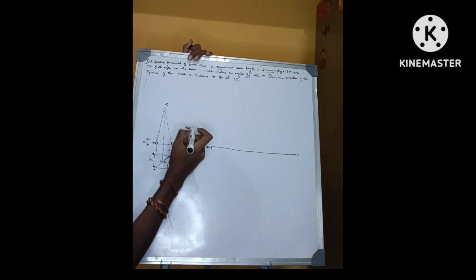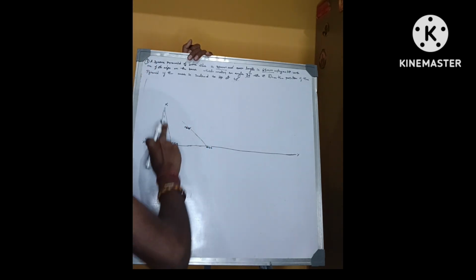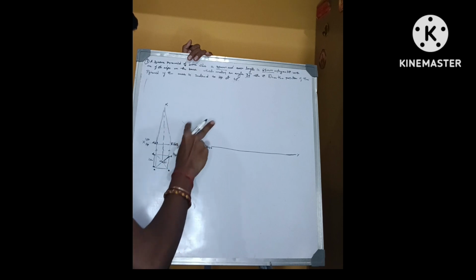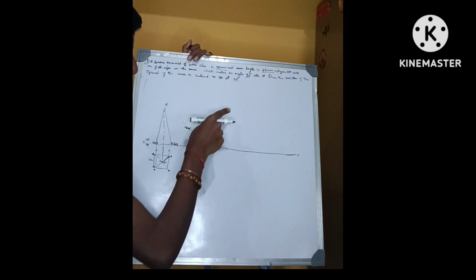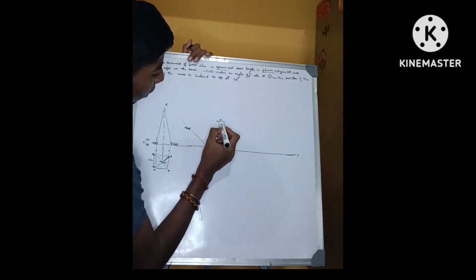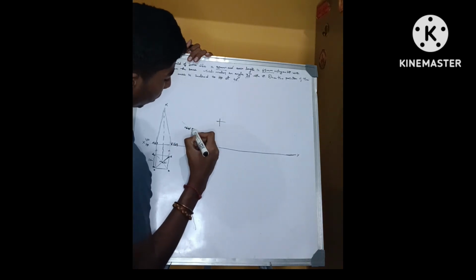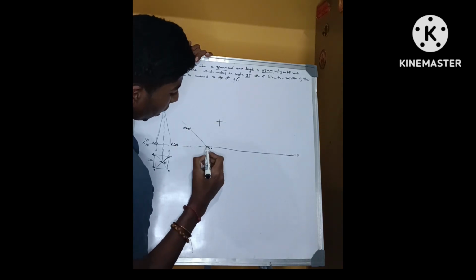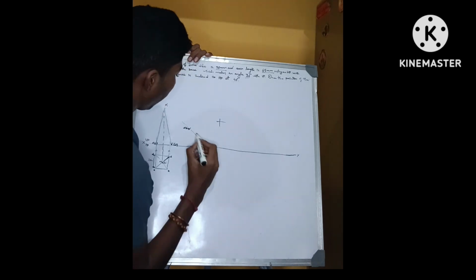When you cut the arc, you will get the point somewhere here. Now take from A to O as a radius, and from here you cut an arc. You will get a point somewhere here like this, and again like this, and next join these points. Let it be A and let it be B.